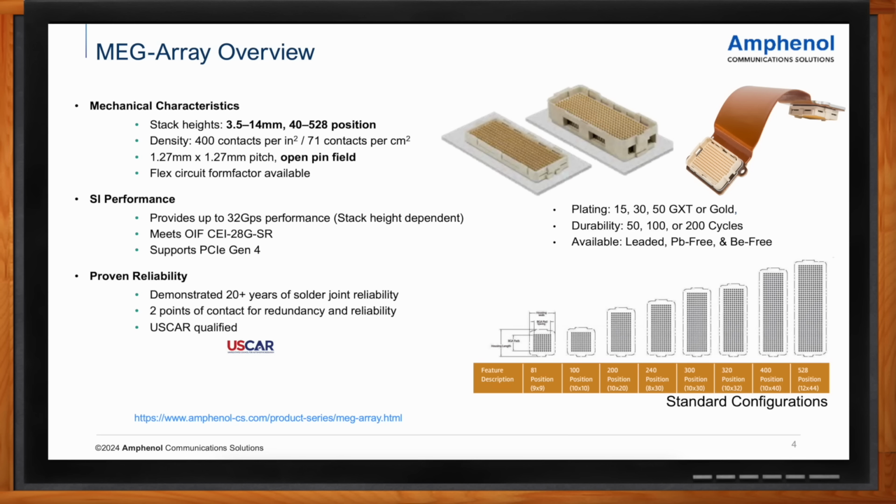In mezzanine connectors, we're often looking at the stack height as well. And that's because the customer might have some other components on the board that they need to vary the distance of that daughter card on the motherboard. So that's why a mezzanine connector will come in different stack heights. So MEGArray is tooled from 3.5 millimeters up to 14 millimeters across all those different pin counts. It's a connector that's been in the marketplace, but it will last in the marketplace for 20 plus years.